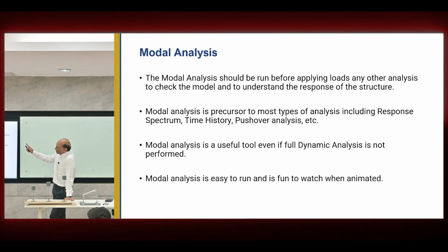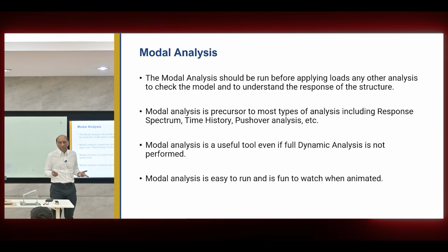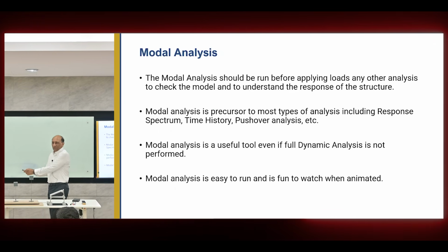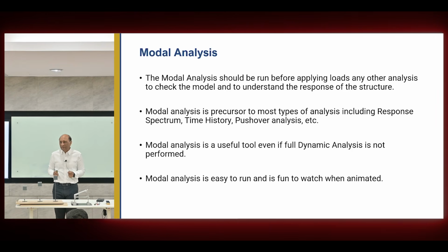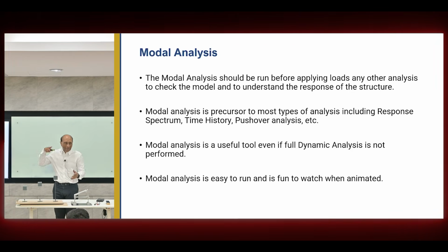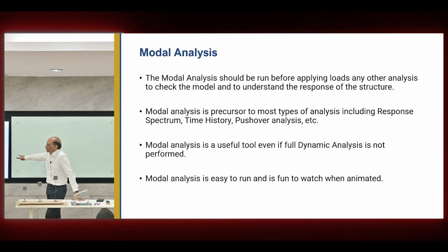Those are very important in tall buildings. Okay, important points. Modal analysis should be run before applying loads. So which means, because modal analysis does not depend on the loads, you must run it before you apply the loads. So you make the model, the first thing you do is run the model and check what's happening. You don't need to apply dead load, you don't need to apply wind load, you don't need to apply live load. No load is needed. As soon as the model is complete, push run and look at the structure and get all the things that modal analysis is useful even if full dynamic analysis is not performed.